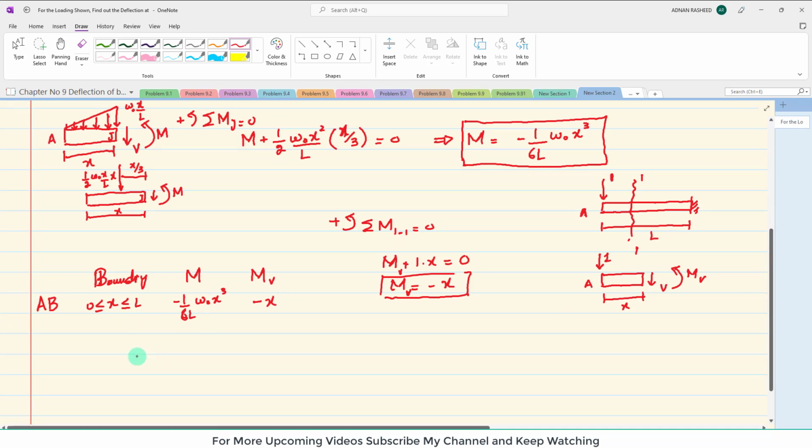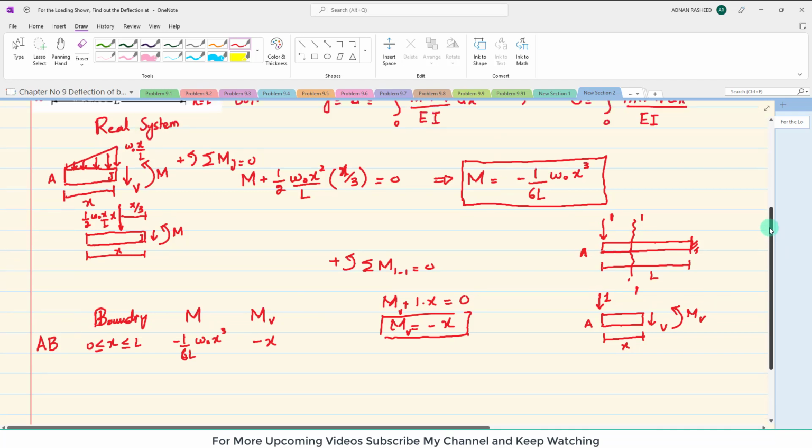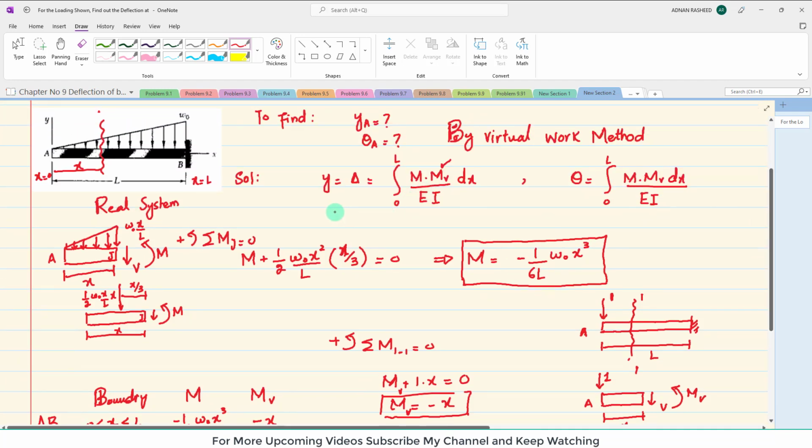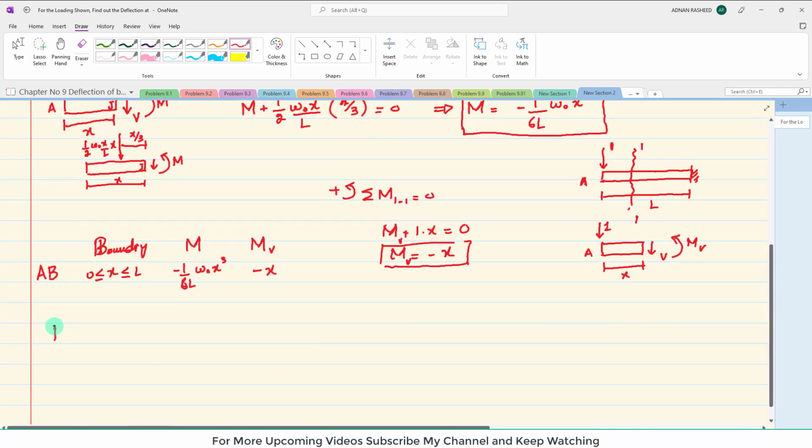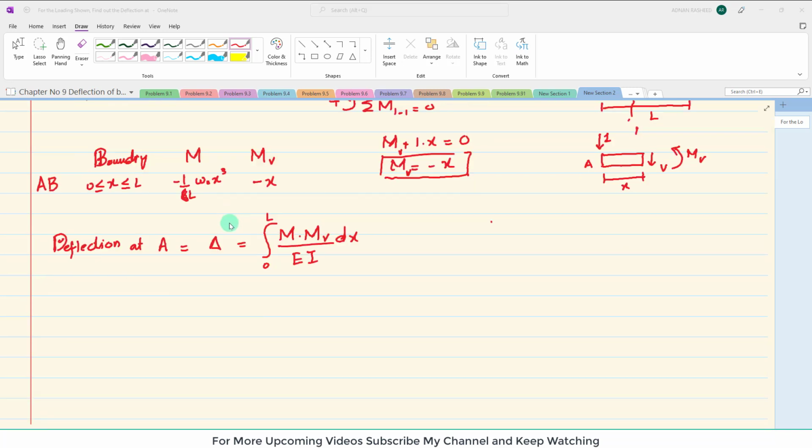Now we will apply this equation. This is the main equation. The deflection at A is delta, or you can also use YA, and it is the integral from 0 to L of M times mv divided by EI dx.